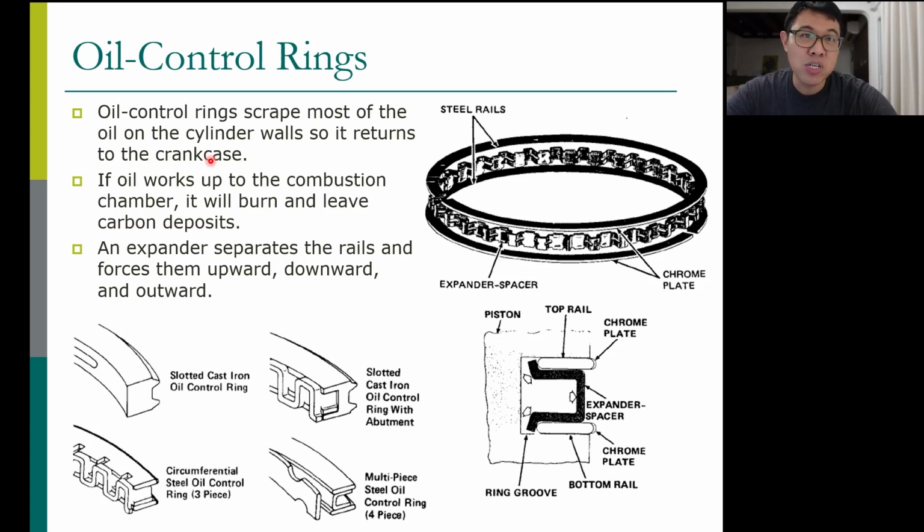And then you create pollution also, right? You lose the lubricating oil, which is not good, and then you create a lot of pollution when you burn lubricating oil, right? Now, normally there is more than one piece of the oil control ring. It has an expander and it has a plate. The plate is used to scrape the oil, the expander is used to push the ring out, right? So to do that you have to push the plate out so that the plate can scrape the oil.